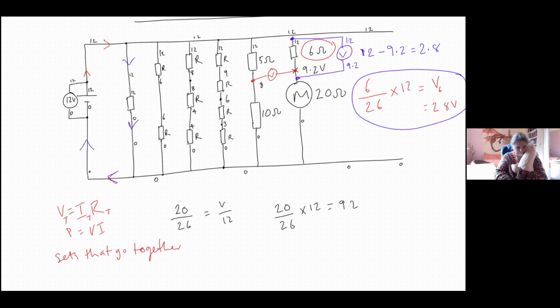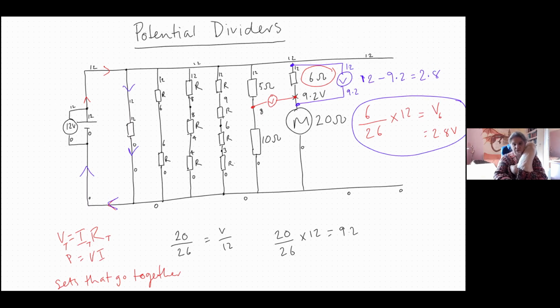Okay, right, so hopefully this has helped you a bit. I mean, there are still other things that you have to remember from year 12. So Kirchhoff's laws. So the currents at any junction add up to nothing. So currents in equals currents out, if you prefer to say it like that. And that's a statement of conservation of charge.